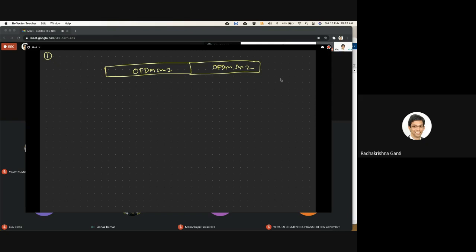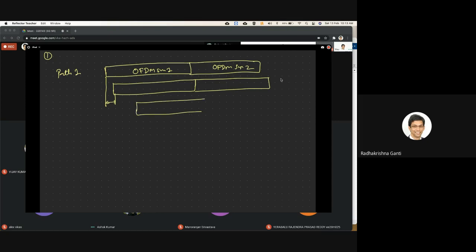This was the direct path, for example path 1. The next one might have hit a reflector a little bit far away and come, so this will get delayed by a little bit. So this is the delay in the paths. The next path might have had a much larger delay. Same, this is symbol 1, symbol 2, symbol 1, symbol 2.